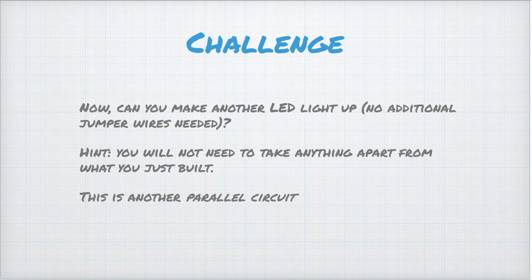Here's a challenge. How do you think you can make another LED light up with no additional jumper wires? Here's the answer. Just add the new LED in parallel to the previous LED.